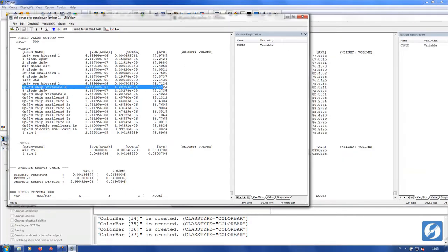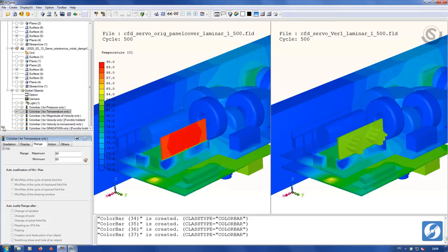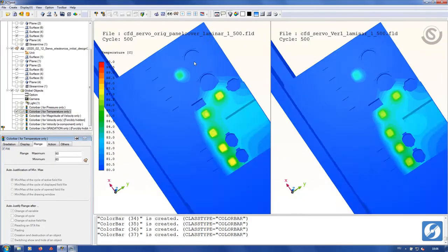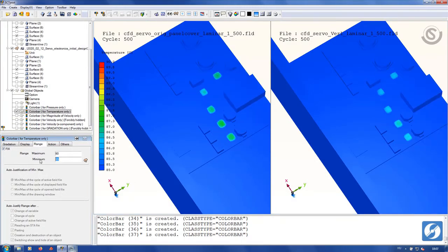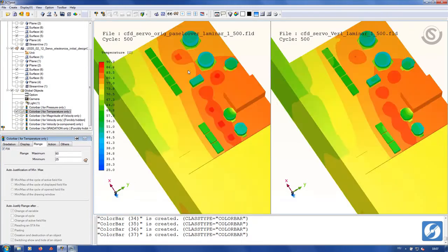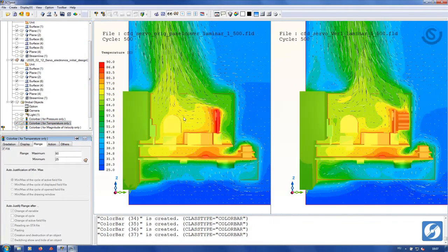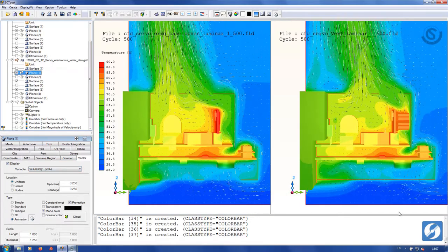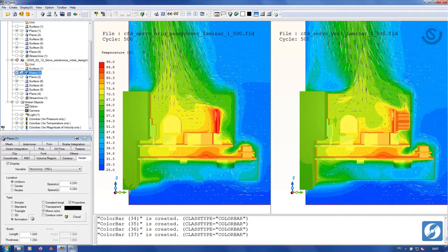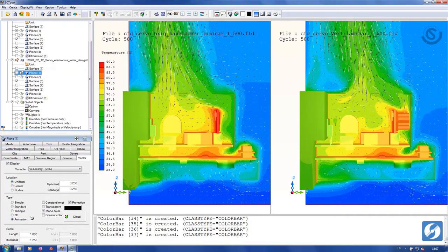Numbers show a 6.9 degrees C decrease, and another adjustment of the scale minimum shows that there is an effect of the repositioned bottom vents, as chips on the bottom card are a tiny bit cooler. The change is between 0.6 and 0.7 degrees C depending on which chip I'm looking at. Airflow around the vertical card is different. Warm air can get out of the casing more easily, but at the end of the day, all that matters is component temperature, so to sum it up, this problem has not been solved yet.